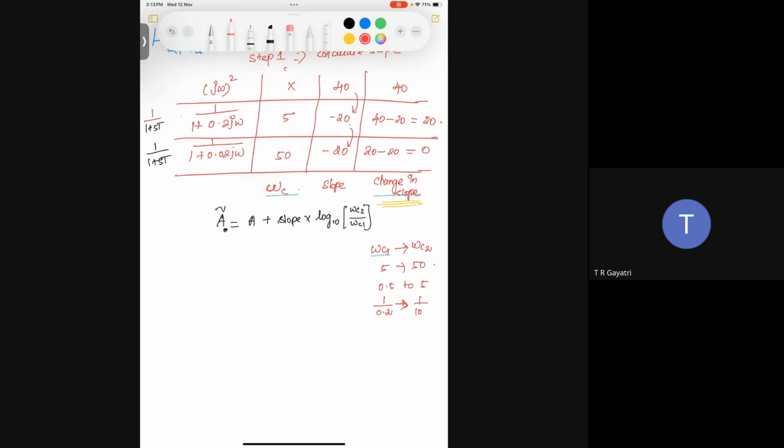The first step is that we'll calculate as we do always, 20 log of g of j omega. Before considering it, I want to introduce two other frequencies, because this corner frequency starts at 0.5, right? So this corner frequency starts at 0.5. The next frequency is 5.